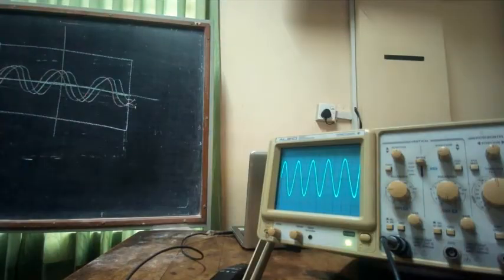Like that, right? So every time you start at a different position. Now, if this persistence is still there, the first one that I drew across is still there. Let's say it only took 5 milliseconds to go from here to there. So this is like 1, 2, 3 cycles, or maybe let's say 2 cycles. If I'm using 1 kilohertz, it will take just 2 milliseconds, and obviously that glow will be there. So all these 3 lines will be there within that 5 or 6 milliseconds or whatever.